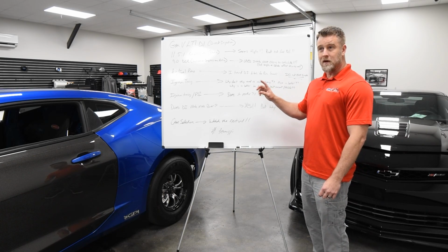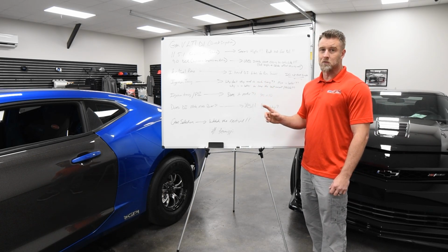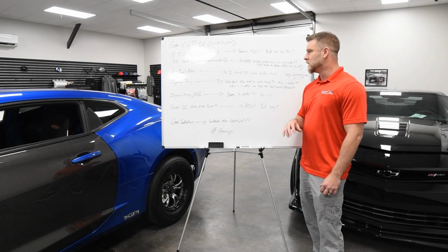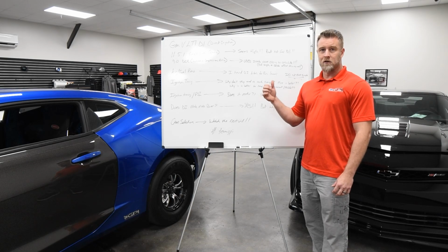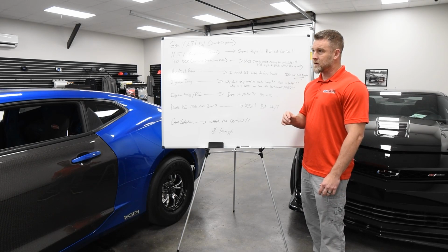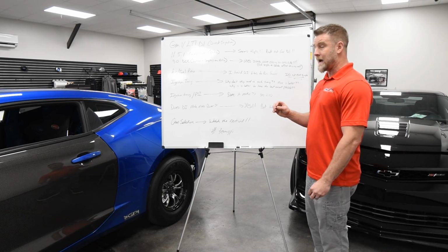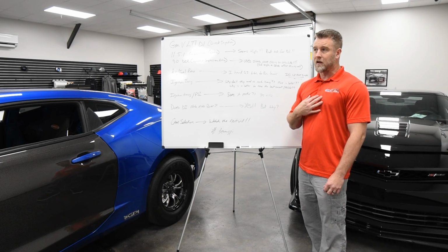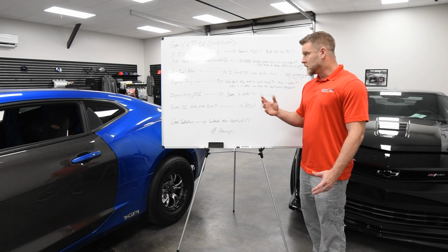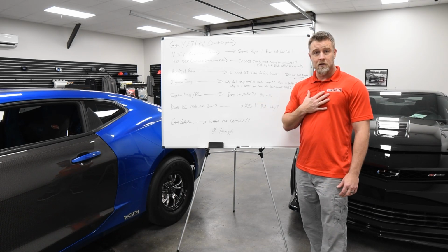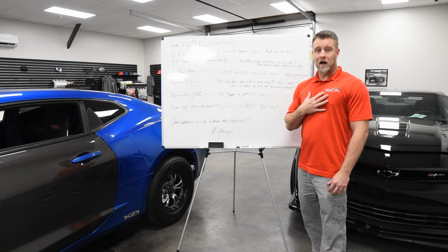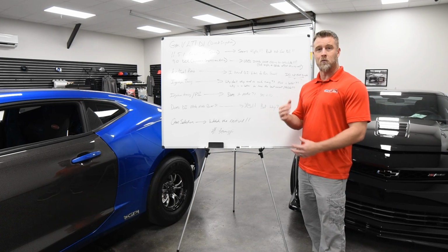Actual air-fuel ratio you measure in the tailpipe is going to be pretty close to what you would have with a port-injected engine, in my opinion anyways. They will tolerate a little bit leaner mix, probably up to about 0.5 point. But for max power, we have not found that they like being much leaner at all than regular port injected stuff. So that's our opinion on it. All of the stuff you're going to get in this video series is going to be our opinion and our beliefs on how we look at this stuff.